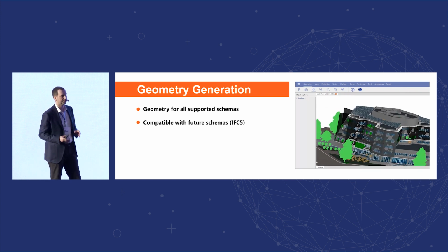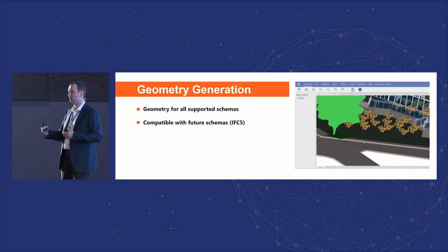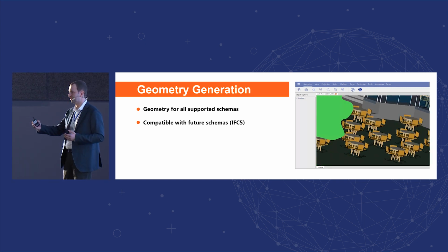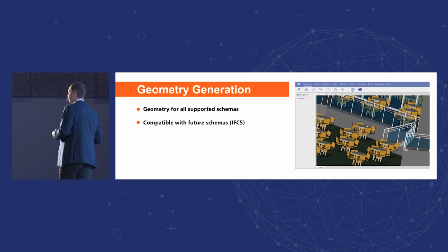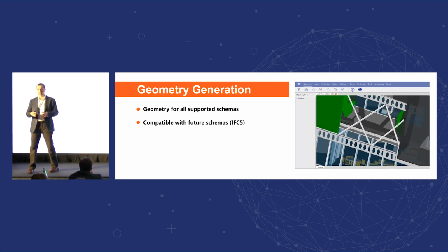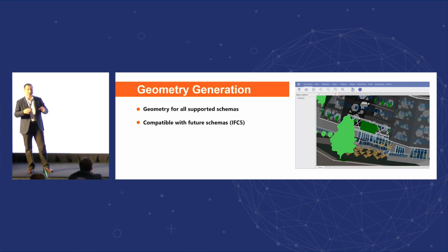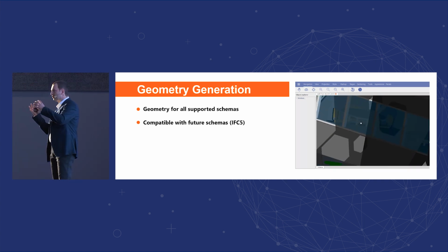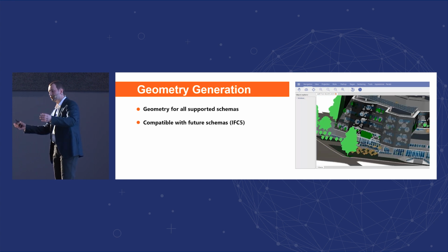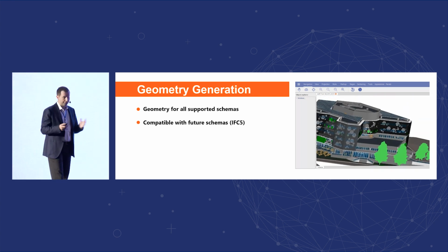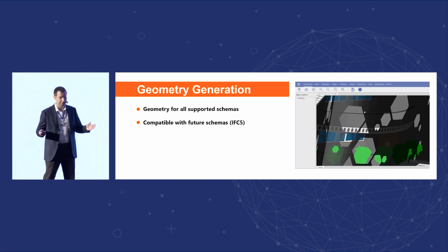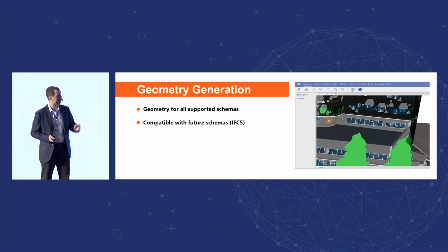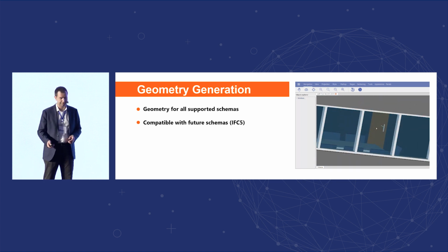So you should do additional processing to generate the resulting geometry. For example, Boolean operations are not presented as a result inside the IFC file. You should perform those Boolean operations to provide the final geometry for the application. And we made this, and overall you see the result on the screen.